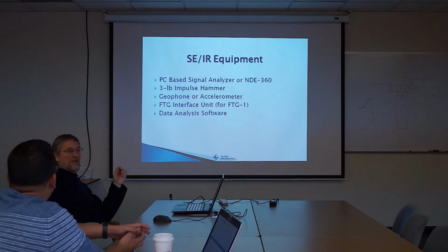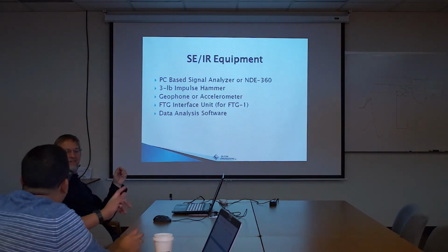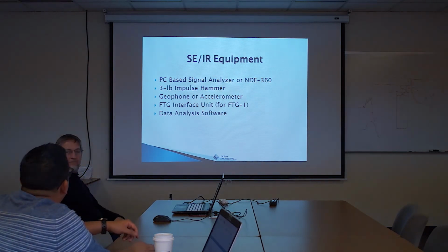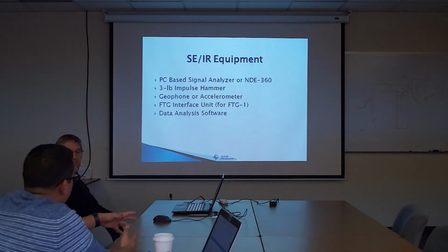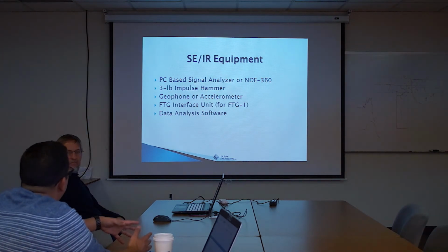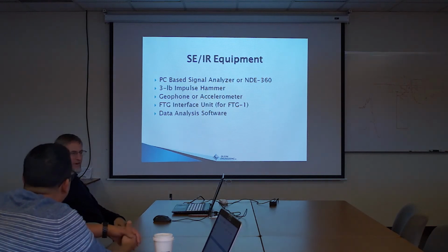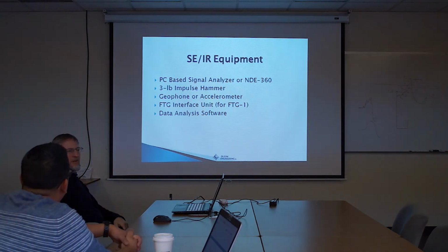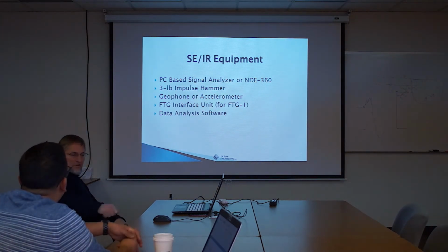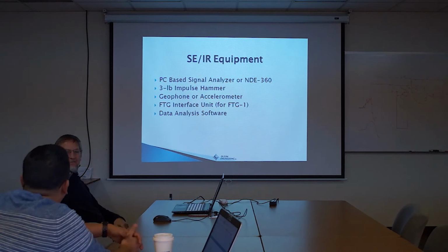It's also a very, very fast log. So we have the FTG. Yeah, you have the FTG one, right? And so I think that they were telling me that anything less than 6 foot on that, it gets really hard. Yeah, 6 foot is kind of the point where we switch over to impact echo, which is a frequency domain test using a little half-pound hammer or a 4-ounce hammer. It's not that you can't do it, it just won't work very well.